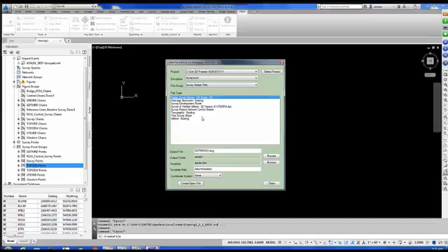All right. Now, this little application is set up, I believe it's reading a text file out there somewhere, and it has different groups, and underneath the survey design file it's been set up that we can create a digital terrain model, a drainage existing file, a survey development model, all the way down to utilities existing. Now, what we're going to do is create something called the survey development model. Now, in this project, at this time, there hasn't been any data placed in the survey folder. So that when I pick on the survey development model, the output file is going to be called servrd 01.